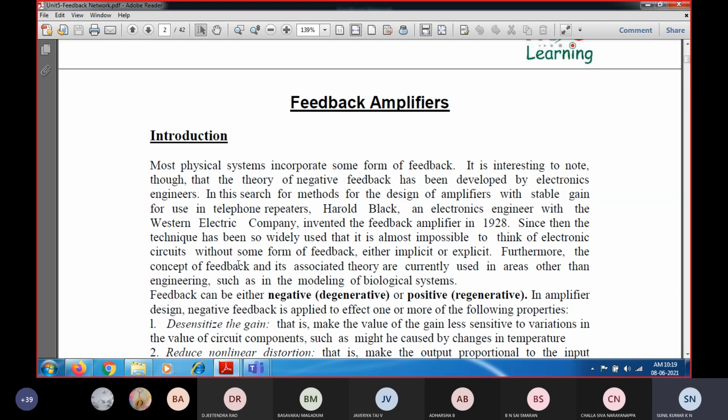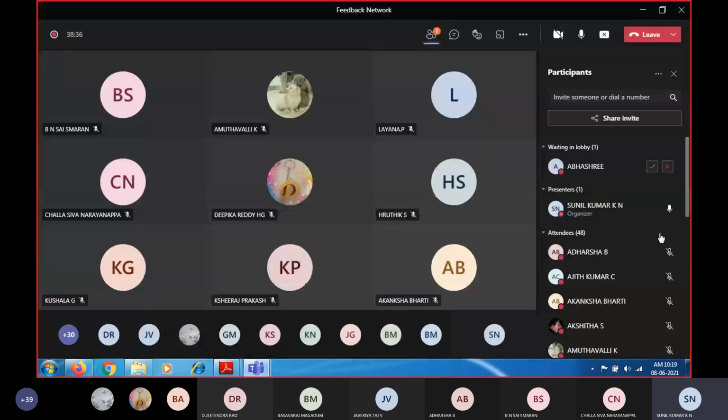As long as the amplifier gain is increased by a factor that is reduced by the feedback network, the loop gain is maintained equal to 1, and you get sustained oscillation. That means you get neither too large nor too small an output.